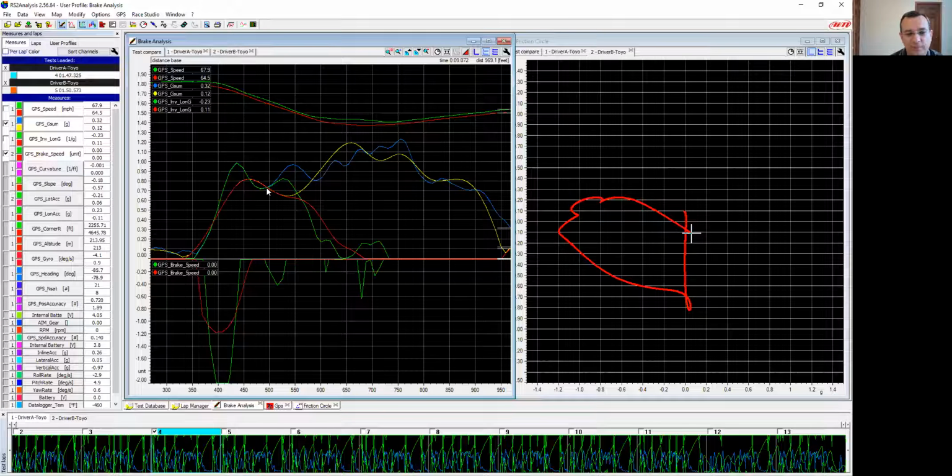But you can also see some of that if you have a steering angle sensor, where you can see that your lateral G, as you're starting to turn in, you're increasing turning the wheel, but your lateral G isn't increasing because you've exceeded the available friction, the available grip at the tire, and turning the wheel is just causing more push. That's a really good use of having a steering angle sensor, and one of the things you certainly want to look at if you have that available to you.